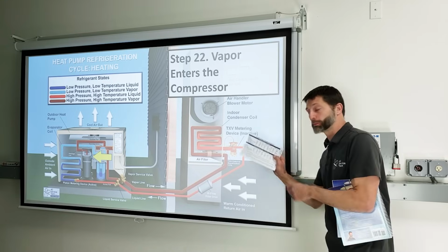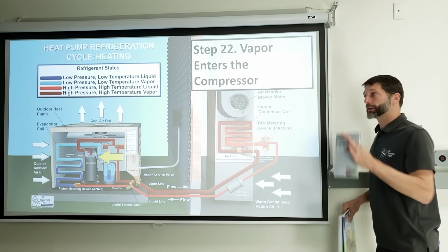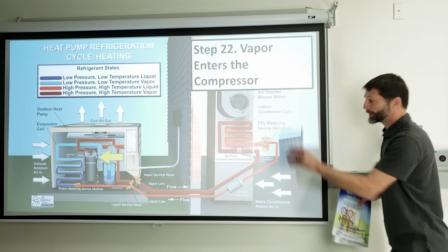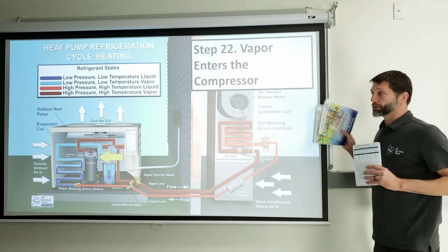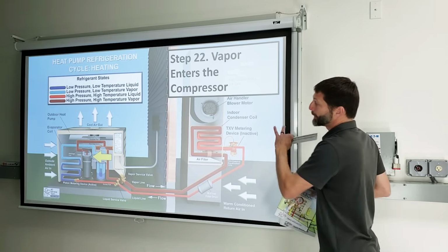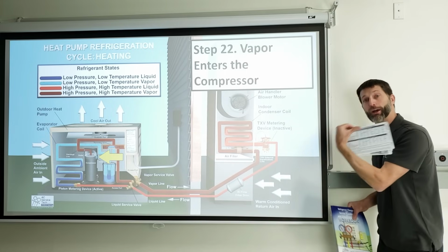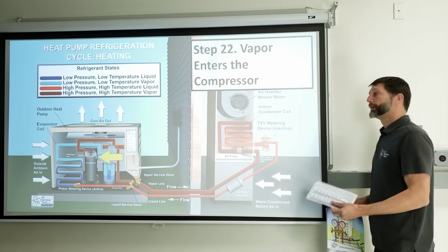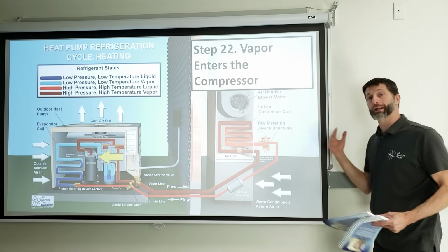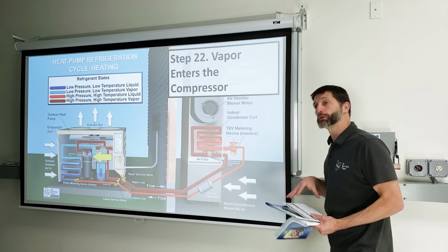The other thing is we have a troubleshooting chart right here, which is the whole point of what I'm saying. Whether you use a digital set, test probes, analog or compound gauges, anytime that you are checking the refrigerant charge and measuring your voltage and your current, just doing an overall check, it's very important to think about the refrigeration cycle and what your measurements really mean. And we also have this troubleshooting guide to help you along with that. So if you have high pressure or low pressure on the vapor line or the liquid line, your superheat or subcooling is high or low, your amps are high or low, or your indoor coil is frozen when you arrive to the site, it's going to help you diagnose those problems.